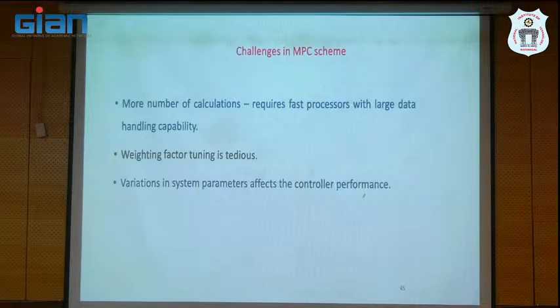If the prediction depends on the machine equations, then these parameters may change based on operating conditions, so whatever torque and flux you predict will not give an accurate value. That's why they are trying to predict the torque and flux profiles even without a model. There are a lot of research papers; if you want, you can go through them.